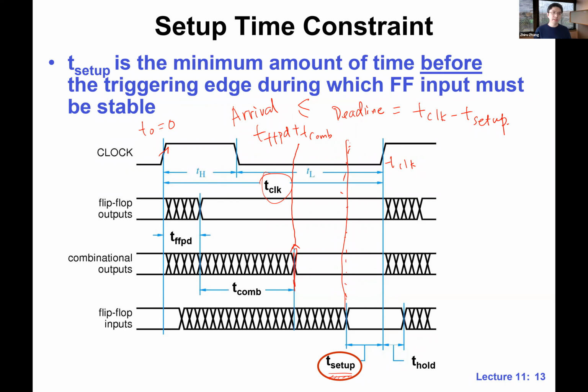If it's still not clear, here is an analogy for the flip-flop propagation delay. Coming back to the exam analogy, it's sort of like the time you need when we give you the link of the exam, the time you need to open up the link to basically open the exam. And then TCOM is the time you need to actually do the questions, solve the problems. And setup time is like the time you preserve for scanning the exam. After you scan and upload to CMS, you don't want to throw away your exam right away, just in case the TA finds that the exam you uploaded to CMS is corrupted. You also want to keep it for a while. This is not a precise analogy, but I hope it is somewhat helpful.